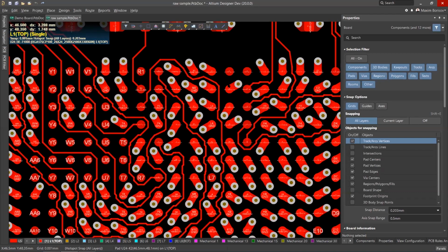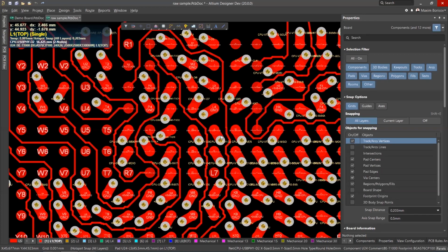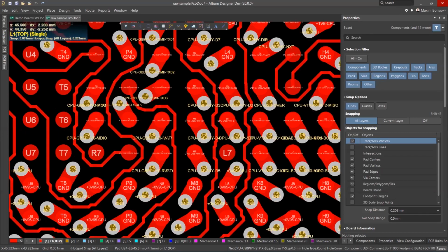And this probably is the kind of challenge that a classical implementation of snake routing can handle. No chance it can, because all existing implementations of such routing techniques rely on a symmetrical channel in surrounding obstacles. And if you start your regular routing procedure in an environment like this one, it just won't handle that. But Altium Designer can.